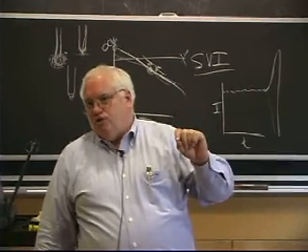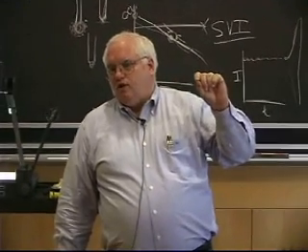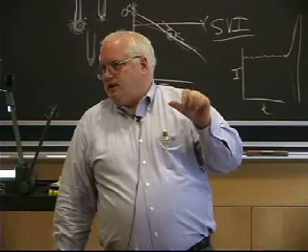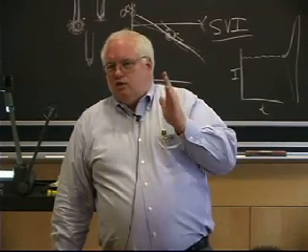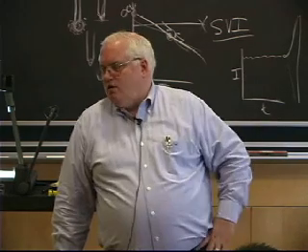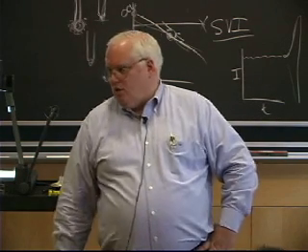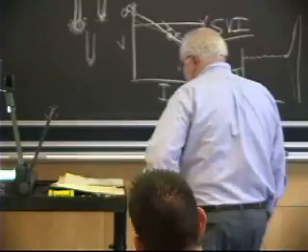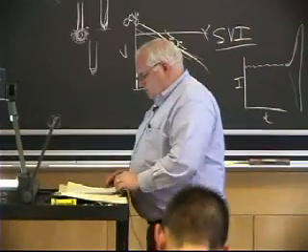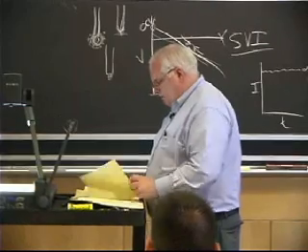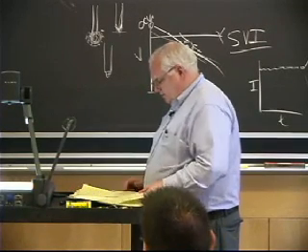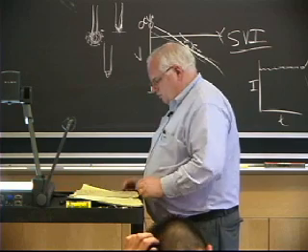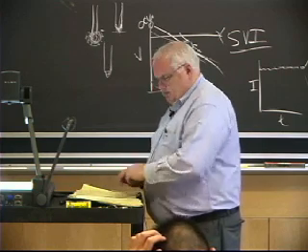On these things, you can either run the RF current continuous through the whole weld if you're doing AC, or you can just do it for the first 5 or 10 seconds, and sometimes they'll have a little adjustment on there. So for the initiation of the arc, you have the high frequency to help you initiate the arc, because you don't want to have to touch your tungsten into the workpiece, and that'll mess up the tungsten tip. So arc starting is not as trivial as you might think in welding power supplies. It gets to be a problem, particularly with robotic welding, but we have essentially resolved that in recent years.